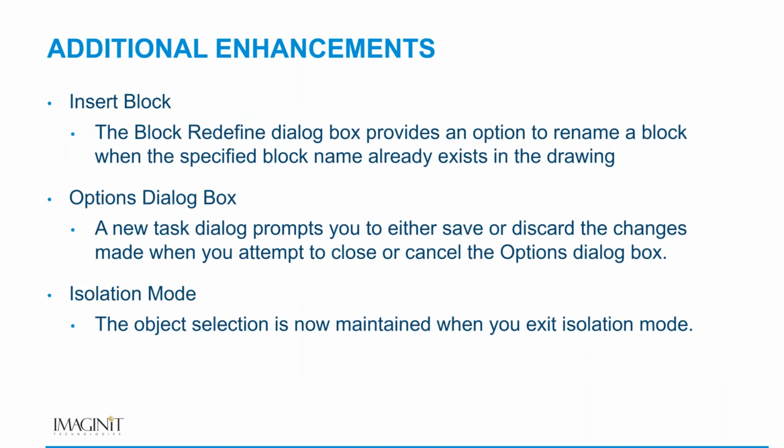So a couple of additional enhancements: the insert blocks. So the block redefine dialog box provides an option to rename block when the specified block already exists in the drawing. This is for insert block. This is also if you're making a block with the same name of something that already exists, it will prompt you if you want to rename it rather than just fail.